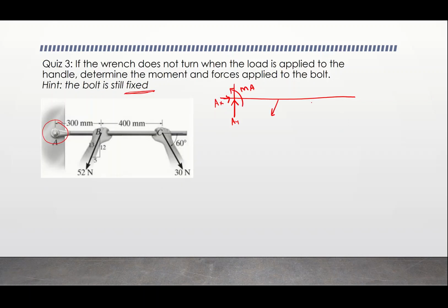So these loads are coming off like this. That's my arms pulling them. They're not exactly at the Y. My elbows are a little cockeyed, whatever's causing that 60 degree and that fraction format. Okay, but I'm pulling a little bit to the right, a lot to the left, a little bit to the right and to the left, but all of it's coming down. And so that bolt, because it says it's not moving, nothing is working here, this force is not enough to move that bolt, that means that everything is going in the positive AY direction.